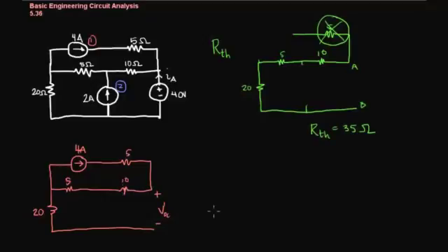Okay, now let's notice that this whole entire branch down here, not connected to anything, isn't contributing at all to the voltage in the circuit. So we could take this negative terminal of V prime and bring it all the way back down to here, and that's the same thing. Okay, so if we could just calculate the voltage across these two resistors, then we're cooking with gas.